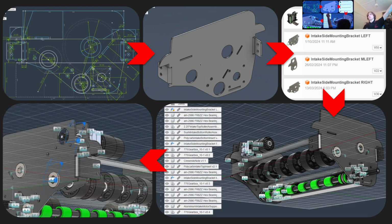unsurprisingly, is a body. Or maybe surprisingly if you've never done CAD before. This one is components. So we make a sketch, we'll turn it into a body, and then we need to handle all of our different files. Once we've turned our bodies into components, we can then drag them into an assembly. And then from an assembly, you can make relationships between joints using motion links to make them move and to actually help you understand and check that all of your moving parts work in practice.